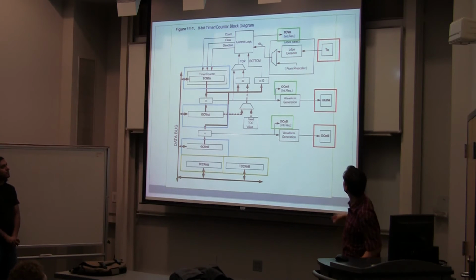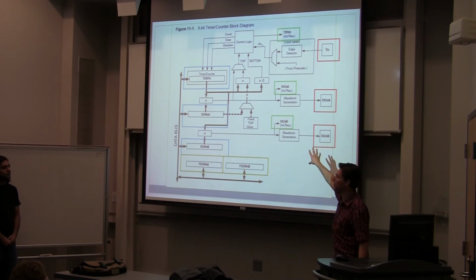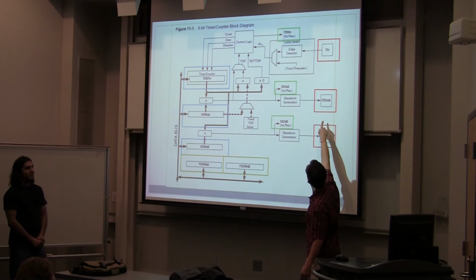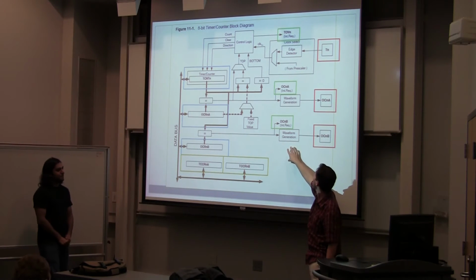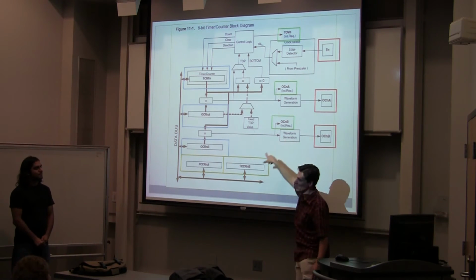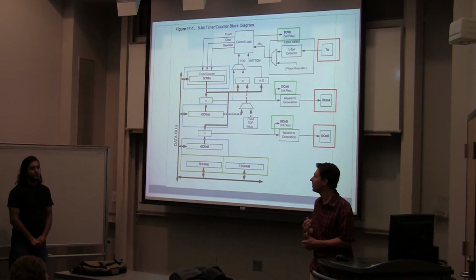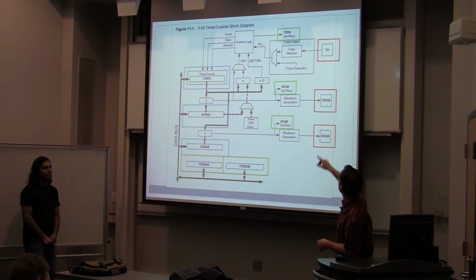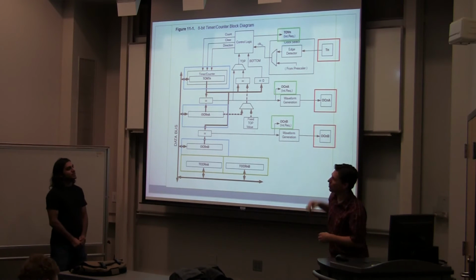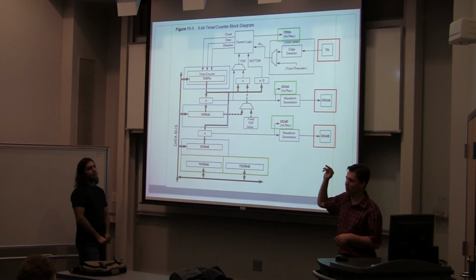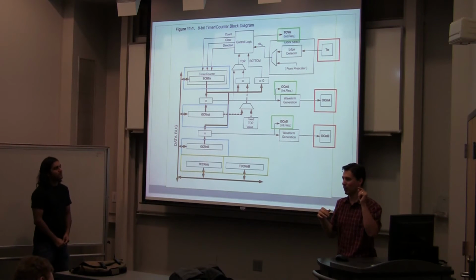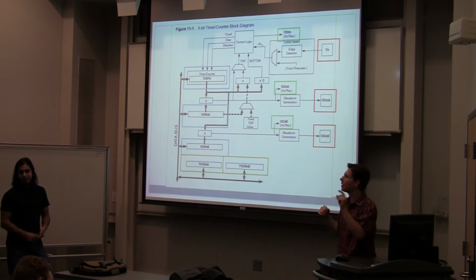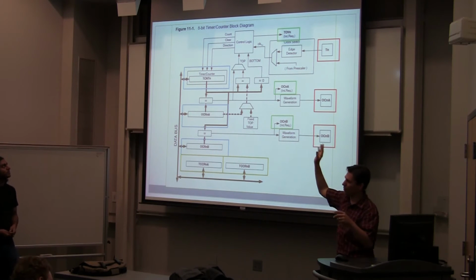And then you have a couple of ways to tie these into actual hardware pins. There's the output compare A and output compare B pins that are associated with this timer counter module. And you see this waveform generation. That's how you make hardware PWM, hardware pulse width modulated signals. And then there's also the Tn, which is just an input source. You can have an external input to count up or count down your timer. So every time you hit that pin, it will count your timer by 1.